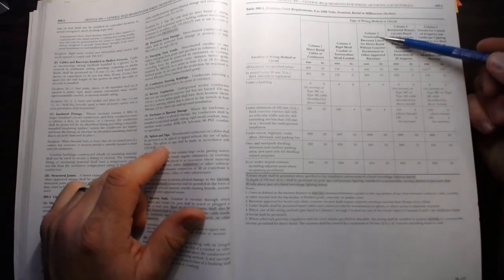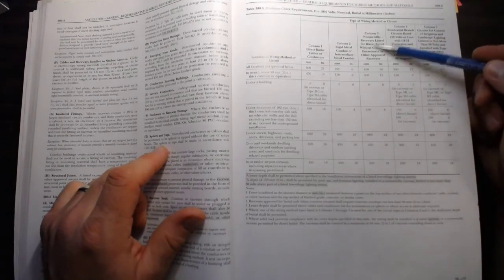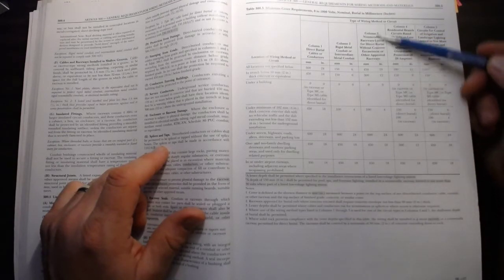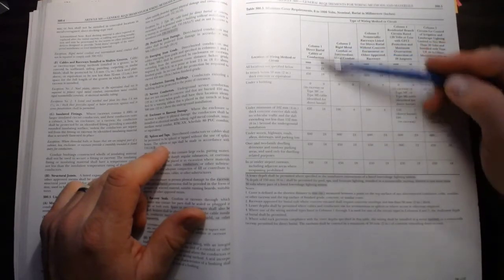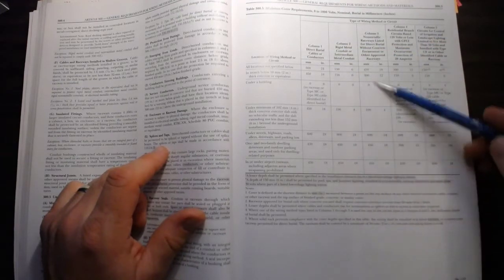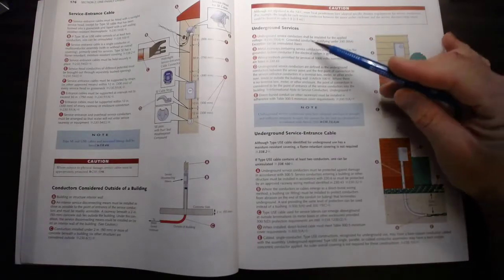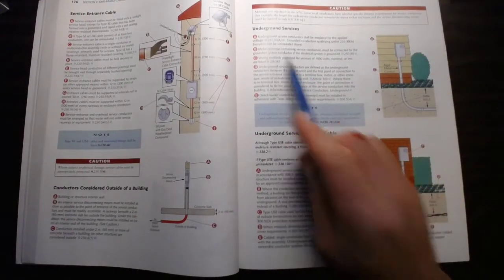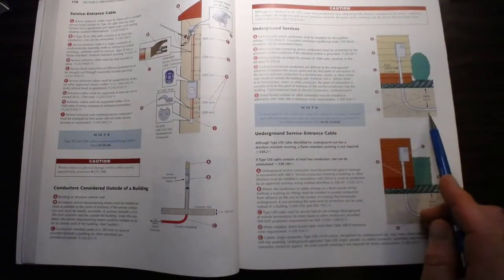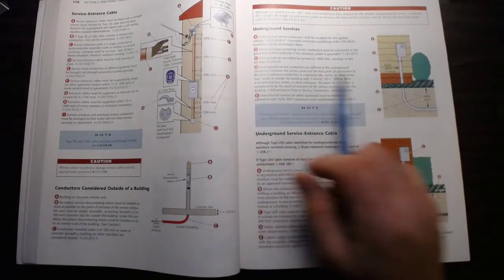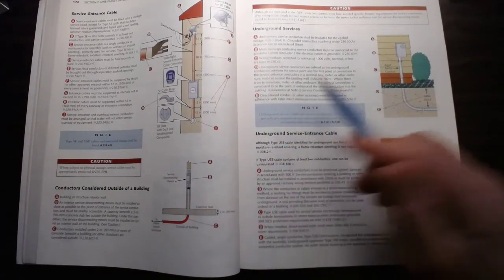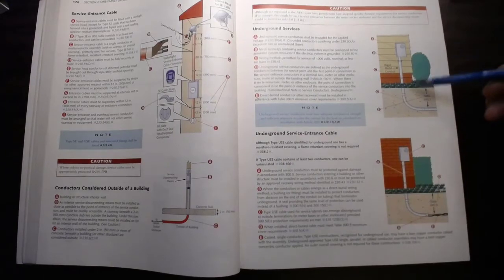In most cases here, in column 3, non-metallic raceway, that's PVC conduit. So you have PVC, you have metal, and you have direct buried. That will give you a better understanding of the depth that you're looking at. So again, table 300.5. With our service entrance conductors, we do have to meet table 300.5. But we also have to look at the electrical service requirements of the serving utilities to find out what size conduit this may be.